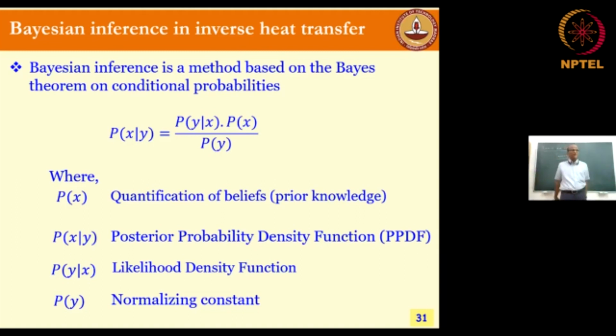You equate all the powers and then find out the dimensionless group. This is called the Buckingham pi theorem. So either by non-dimensionalizing the original equation, or by using the Buckingham pi theorem if you don't have a forward model, you can find out what these dimensionless groups are. Even if you're a data scientist, you collect all your dependent and independent variables in the form of these dimensionless groups and correlate the dependent dimensionless groups with the independent dimensionless groups. Dimensionless temperature is correlated with the fin parameter, ratio of the temperature, something like that.